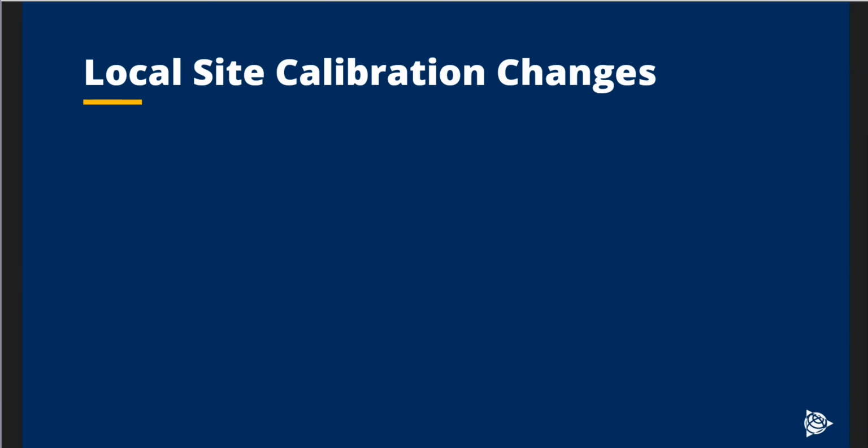Then you take that information and bring it in TBC and decide in the office that you want to change the site calibration, which happens all the time. There, you might need to go in and disable those optical measurements, redo your site calibration, and then re-enable the optical measurements after the site calibration.